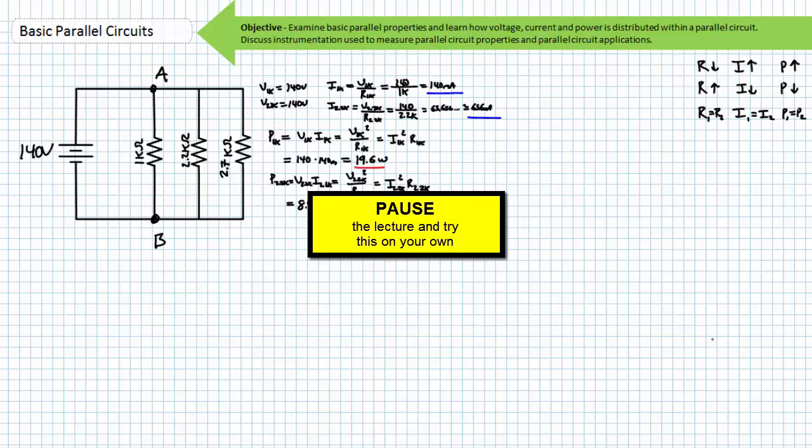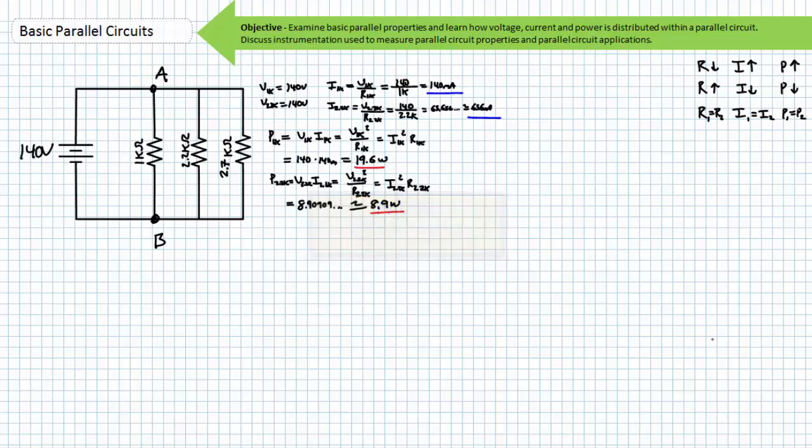There are fundamental differences between the two relationships regarding how increasing numbers of resistors inside these circuits affect total resistance. You do not need to resort to calculations to answer this simple question. Will source current go up or will source current go down now that there is an additional path in parallel? Does the 1 kilo ohm resistor care that there is an additional third resistor in this parallel relationship? No, neither does the 2.2 kilo ohm resistor. Both these resistors continue to draw their respective amounts of current, and only the source is aware that it must now provide more current for another electrical load.